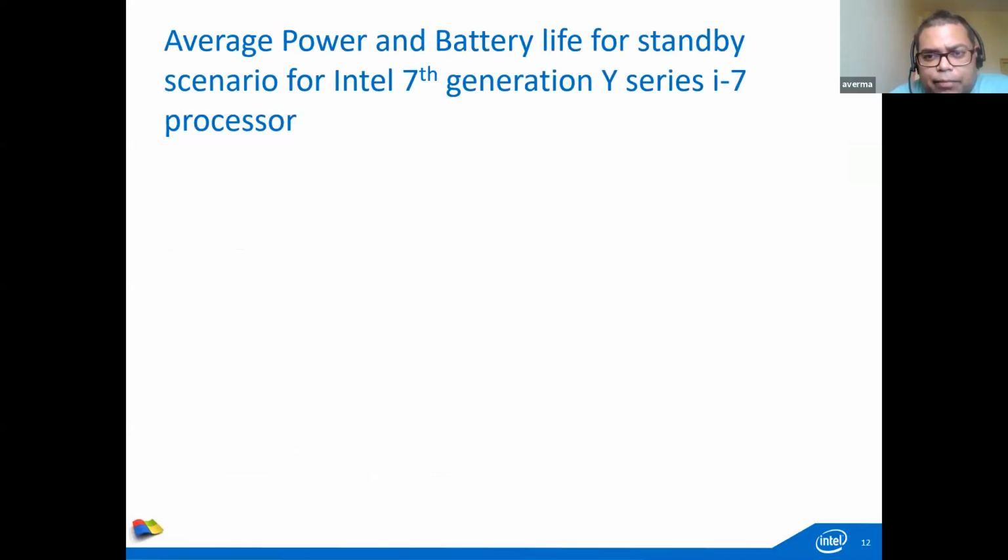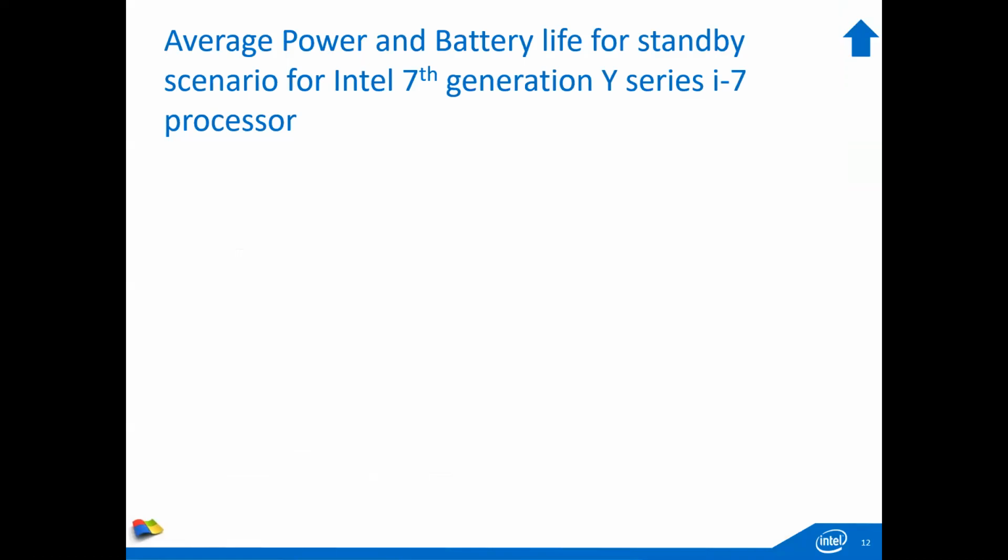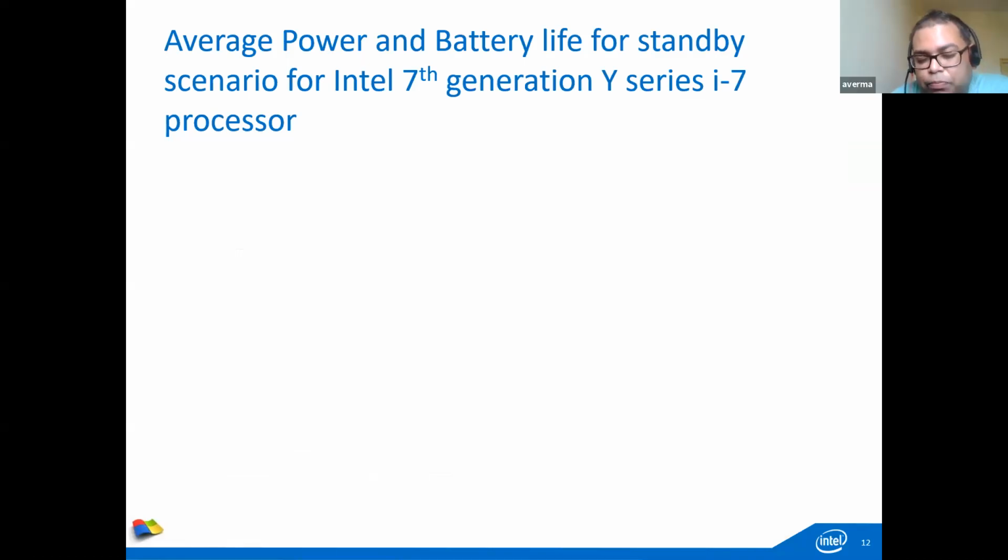Okay, so I think that was pretty good actually. You guys understood the concept of how to calculate the battery life, or get the corresponding average current and then convert it into the power. That's your basic power and current requirement for that use case, which we engineers basically optimize that use case for. I think that's the basic.